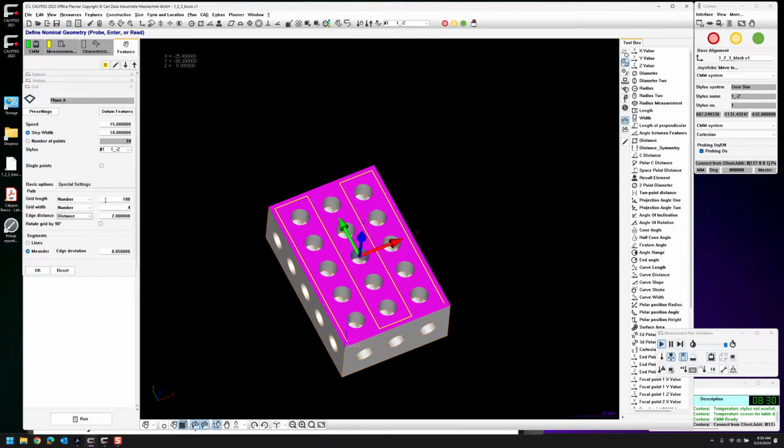And other than that, let's go ahead and go with a step width. Typical step width is going to be a maximum of 0.25 millimeters while scanning. Basically, we're going to use our filters with a 2.5 millimeter wavelength on the filter. We need to have 7 points per wavelength for the filter to activate properly. At 0.25 step width, that actually gives us a total of 10 points per 2.5 millimeters. That way, when outlier elimination activates, it won't mess up our filter.